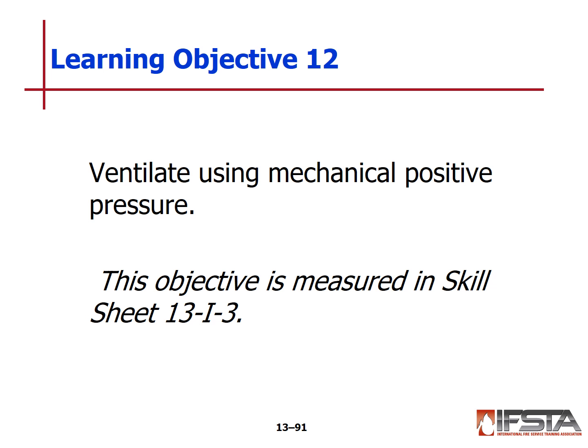Make sure it starts, shut it off, take it up, restart it on the roof. Okay? Because you don't want to get on the roof and have it not start. So always start them on the ground first, shut them off, because another dumb moment, don't climb a ladder with a running saw. It's a dumb moment, but you know what? There's a warning label out there somewhere because somebody done did it.